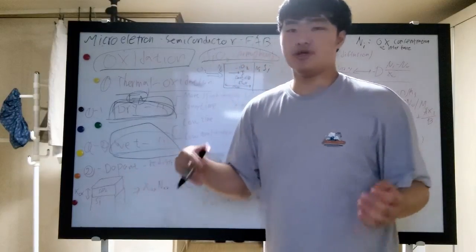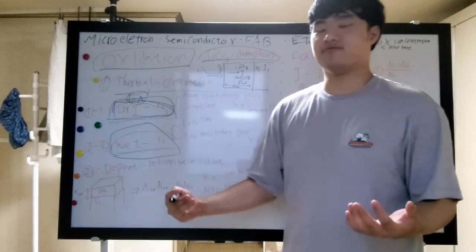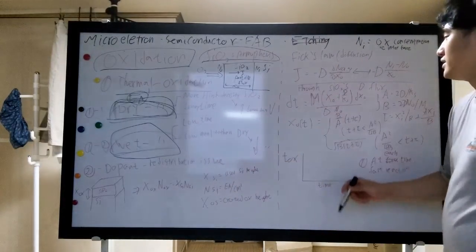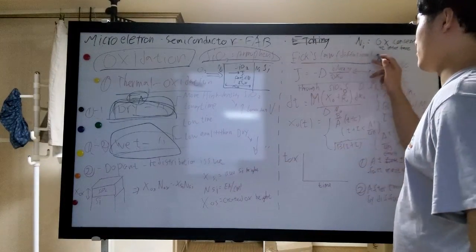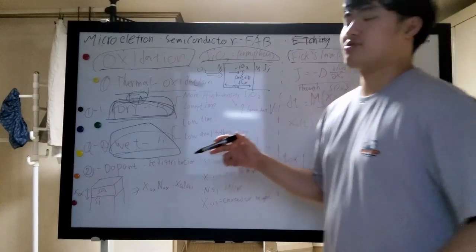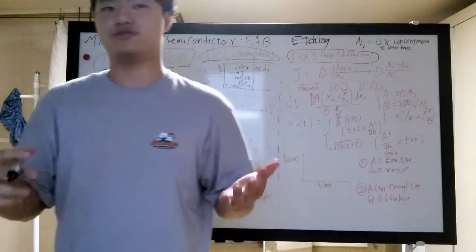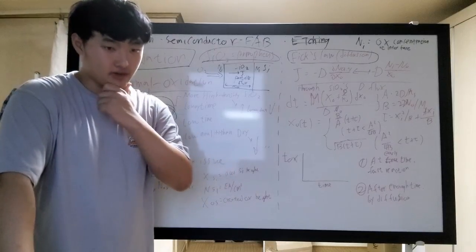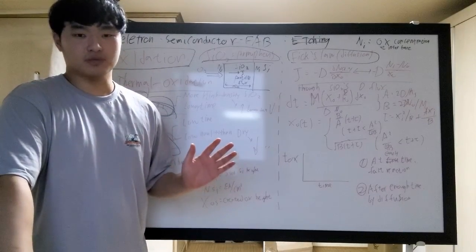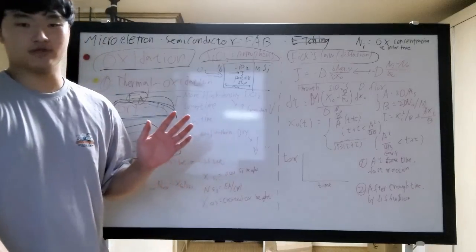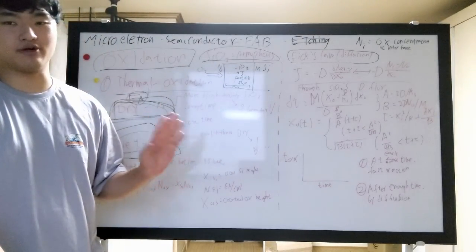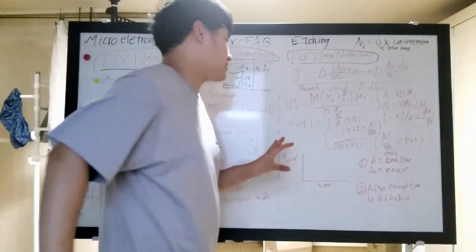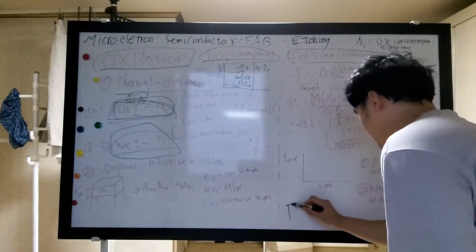When doing the oxidation process, there are some important factors you must know. So see the equation of Fick's law. Fick's law is related to the diffusion process. If we talk about diffusion, diffusion happens due to the difference of concentration between metal A and metal B. Just taking the example of the p-n junction.